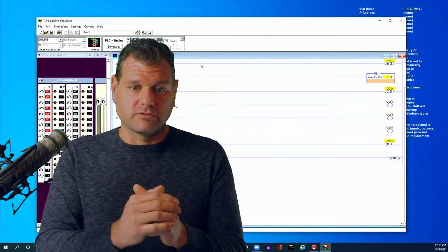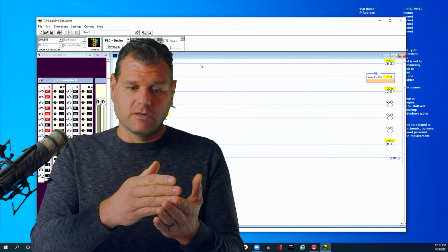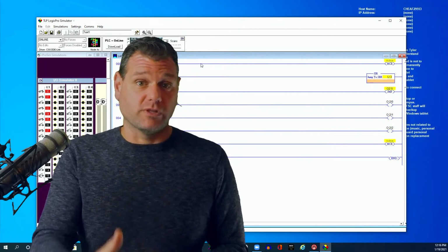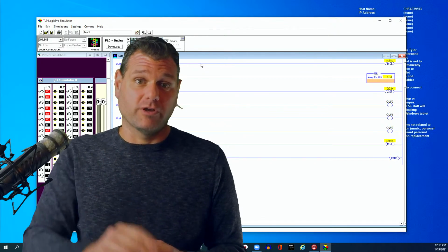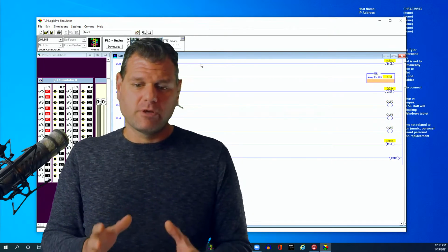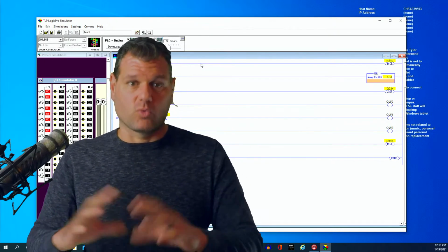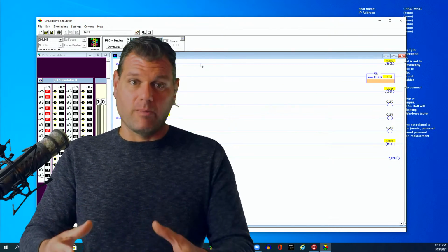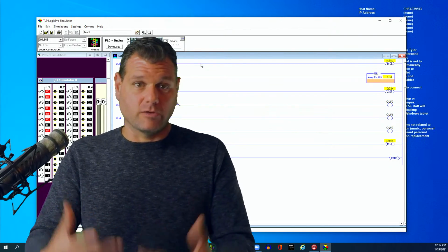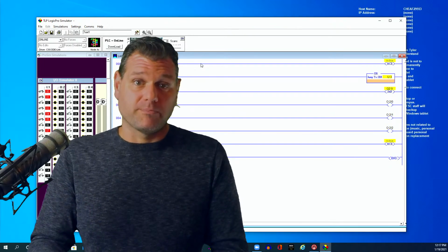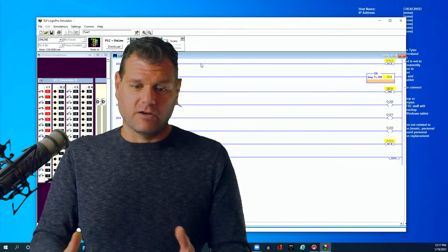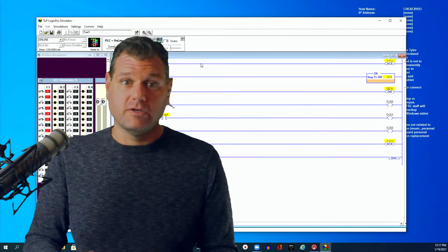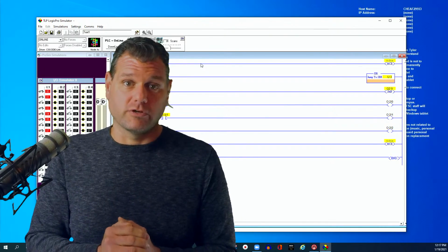There's another method I'll show you in a second. But you could do that and say, okay, I'm going to take it out of the code altogether so it doesn't rely on that. Or you could force the output and say the output needs to stay on. Typically, when you force things, you're going to be around it. Like you're actually going to stay in that area and watch it, because if the tank of a sump pump goes dry, you're going to burn your pump up, right? If it's a fan and something happens, there's nothing going to shut that system off by itself. So you physically got to go in there and actually do your stuff.